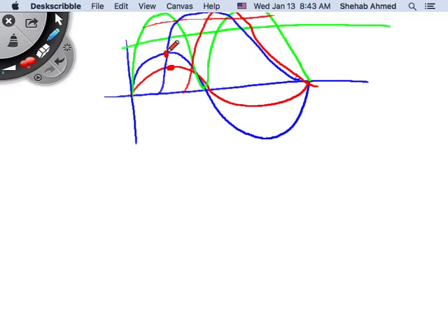So for single phase, I selected conductors that can withstand a certain voltage and current, but I had a low value of average power. Versus I buy a three-phase motor, and wow, it's amazing. For the same conductors that I'm using, the same insulation and same current carrying capacity, I get a much higher power density, because of this idea of pulsating power in single phase versus the non-pulsating nature of power in three-phase systems, right?